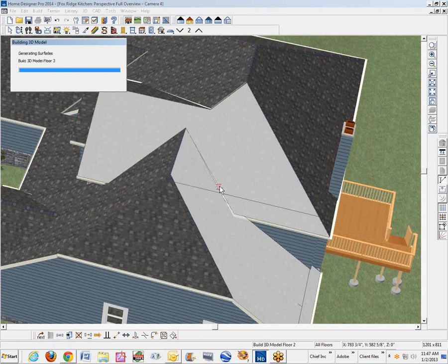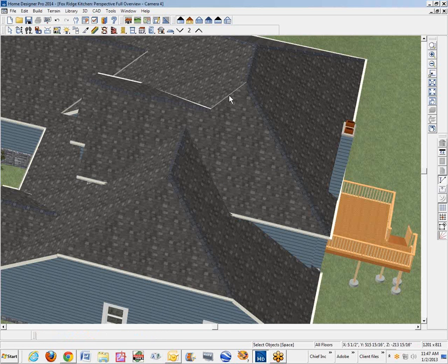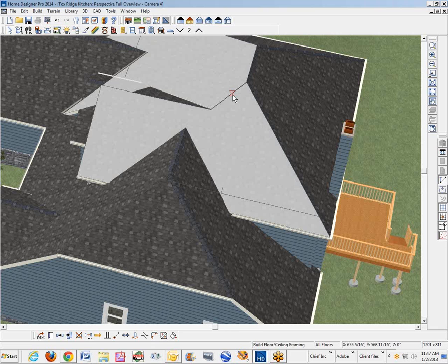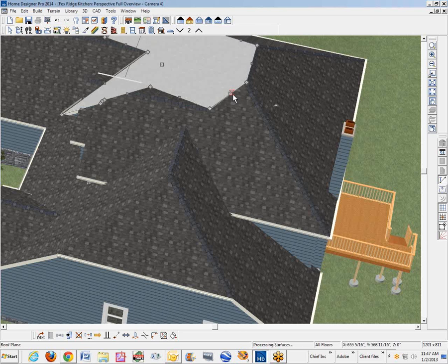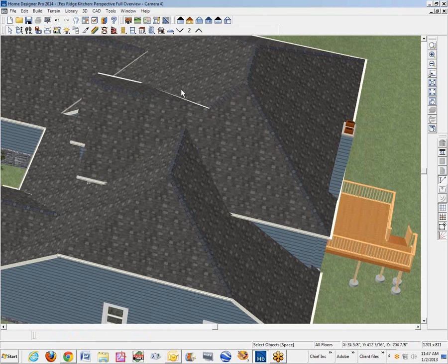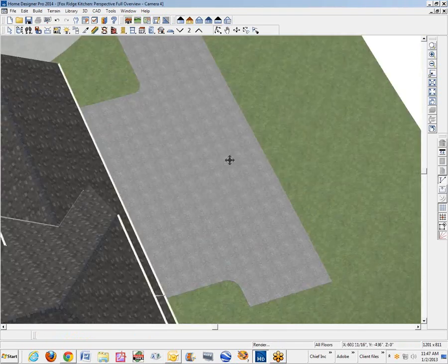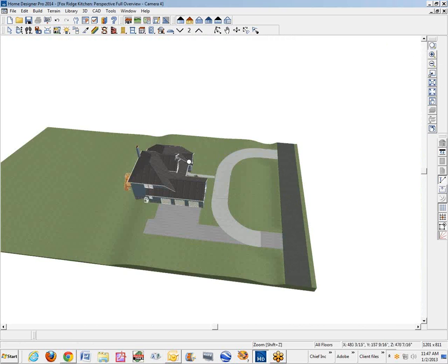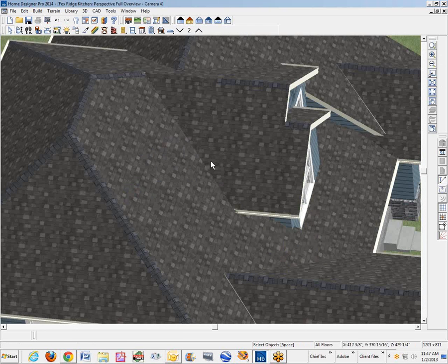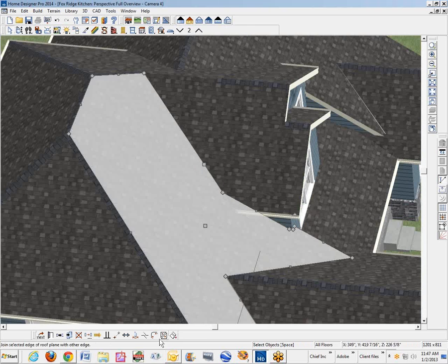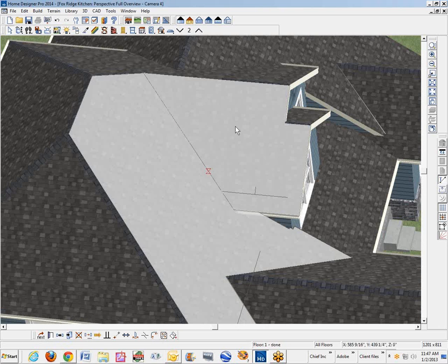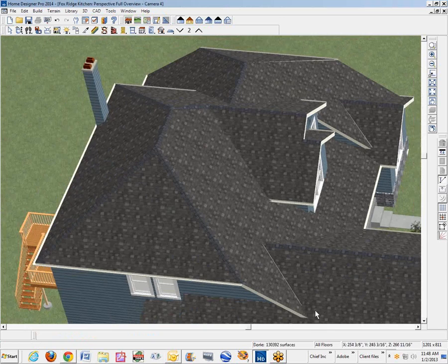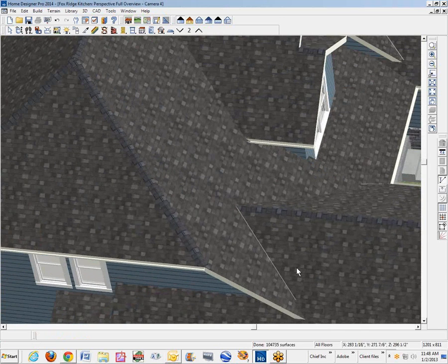And this didn't add up to fixing your open below problem. But this is the sort of thing I'm talking about that new users are not real aware of. And little inconsistencies, roof joints that aren't properly connected, walls that are not quite straight or properly connected one to another. They add up to instability in the model, and it starts doing things that it's not supposed to do, and it just seems inexplicable. And maybe the software shouldn't be as delicate as it is, but nevertheless, there you have it.